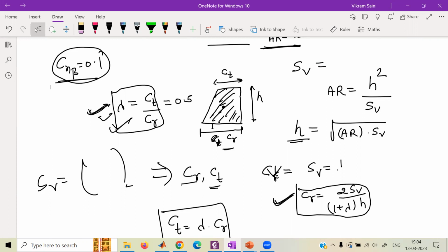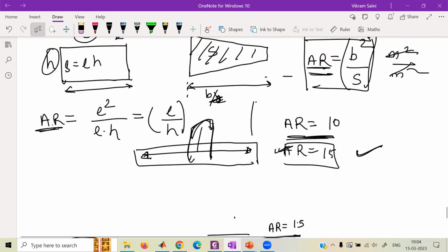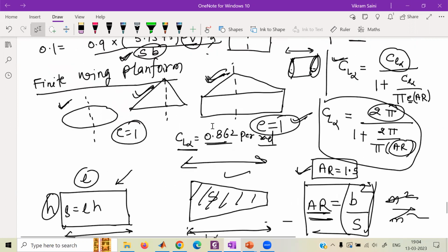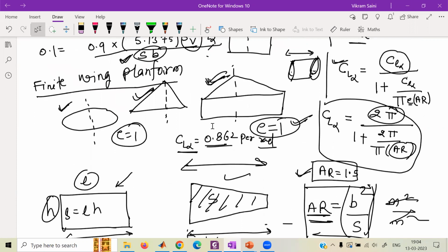You find out the value of that cost function. Cost function is in terms of certain constraints that you have on the design, right? So the idea I'm trying to give here is you formulate an optimization problem where the unknowns are aspect ratio and the taper ratio. And you solve that optimization problem, you end up with answers on AR and lambda. So this whole exercise was to give you a sense that in aircraft design, there will be guaranteed many variables that you have to choose. You don't know their values beforehand.